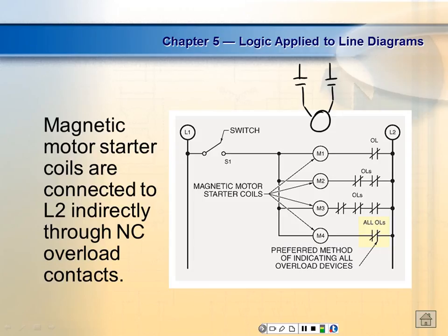So this is the main compressor contactor for a house unit. So this is a contactor, and this is what they do on the thing. So if you work on a house unit, you need to be real careful, because they don't double break the 240 lines.